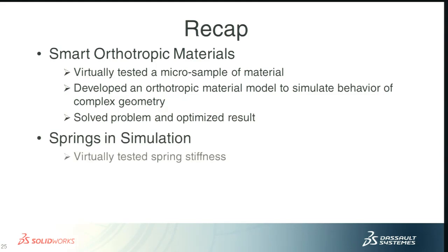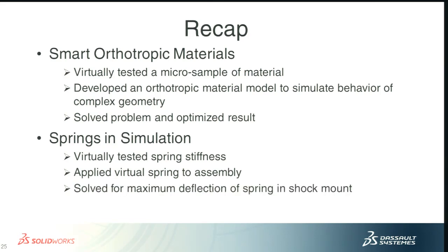In the spring simulation, right, we virtually tested the spring stiffness. We applied the virtual spring to the assembly, right? We then solved for the maximum deflection of the spring in the shock mount, and then we used those maximum deflections to go back and determine the maximum stress and fatigue life of the spring itself.